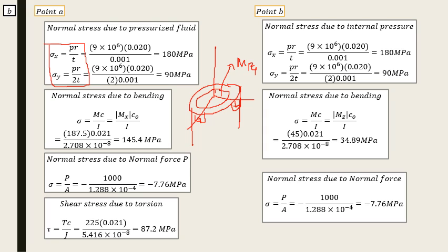The equations are similar, but the difference is that the hoop stress is divided by t, while the longitudinal is divided by 2t, because for sigma x we only use one thickness, and for sigma y longitudinal we use all the parts of the thin wall, so we use the thickness 2t.